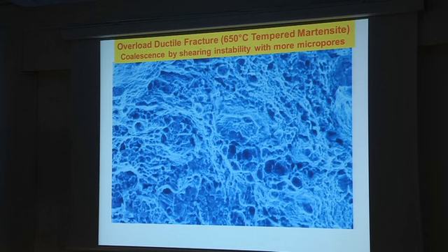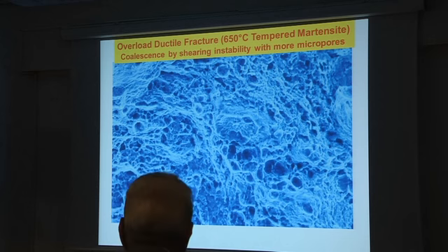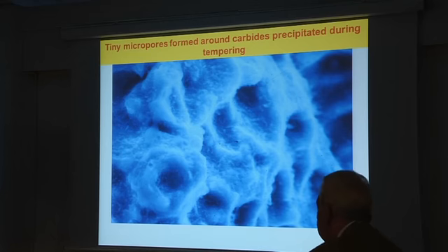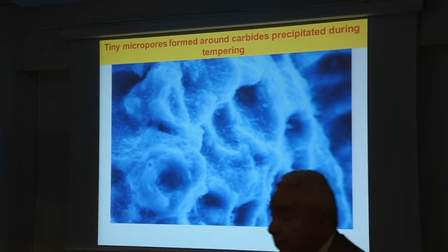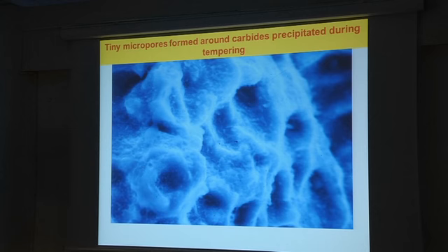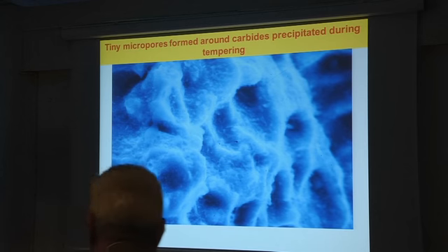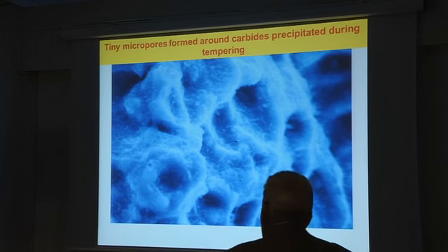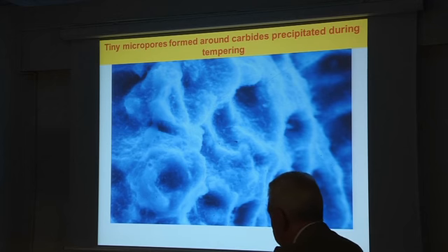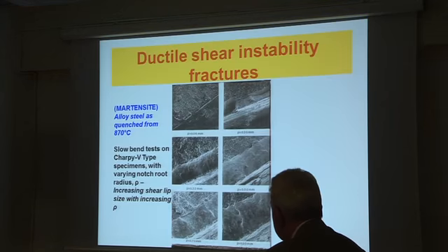If it allows you to have full plane strain, or if it is not large enough and you have some plane stress. Each of the carbides can nucleate one such micropore, and so during tempering you nucleate spherical cementite carbide that tries to activate micropore formation around them.